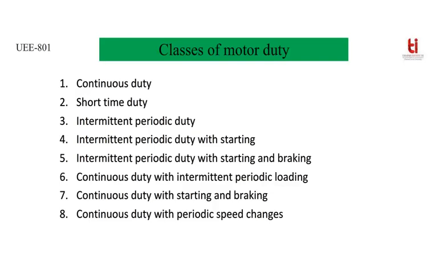Because of that increased current, the temperature rise will be more. Though the heating time constant is very large compared to the electrical time constant, its effect cannot be ignored. That's why intermittent periodic duty with starting is also a class of motor duty.